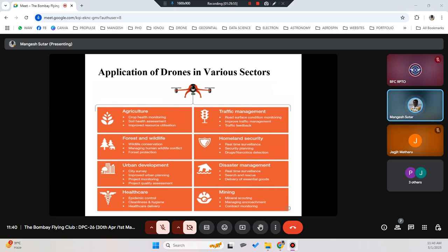They used to talk on the walkie talkie or on the phone and say, okay, please take a closer, more zoomed-in view of the particular tower and give me the real time footage of that tower or its component. A lot of times the insulators were broken, or the wires had got oxidized, or carbon was getting generated because of the sparks, or moisture and all that. All those challenges are there, and a lot of reactive work was happening before the drone flying and capturing the footage.